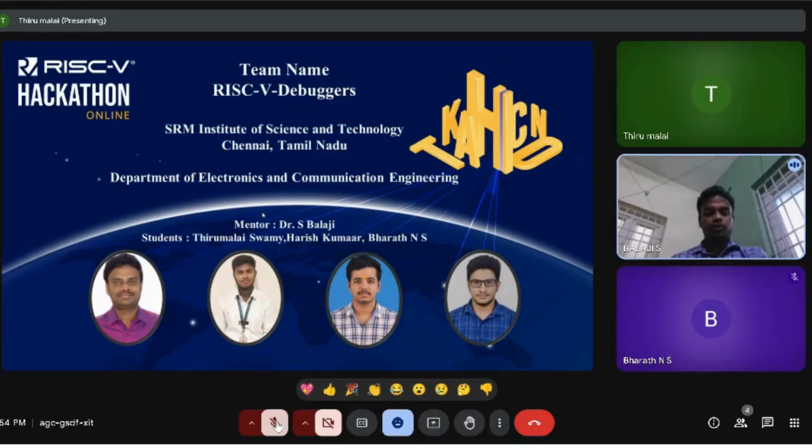Our motivation was to boost the performance of Softmax using hardware specific features of the RISC-V architecture, namely RVV, the vector extension, and ACE, the Andes custom extension, while keeping accuracy intact. We also wanted to build a modular and reusable framework that could be extended to other ML operations in the future. This project gave us a chance to bridge the gap between high-level ML concepts and low-level hardware optimization.